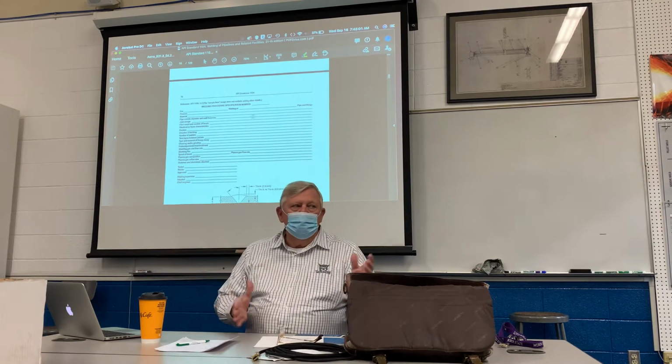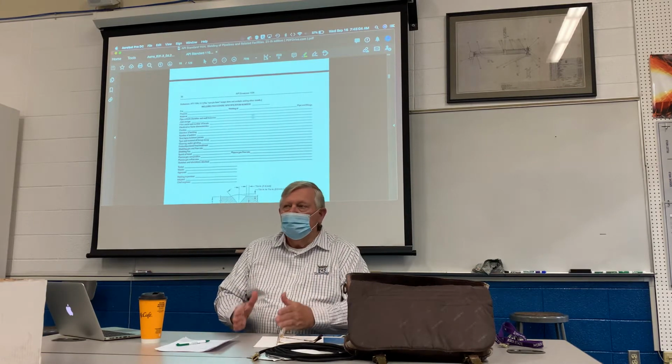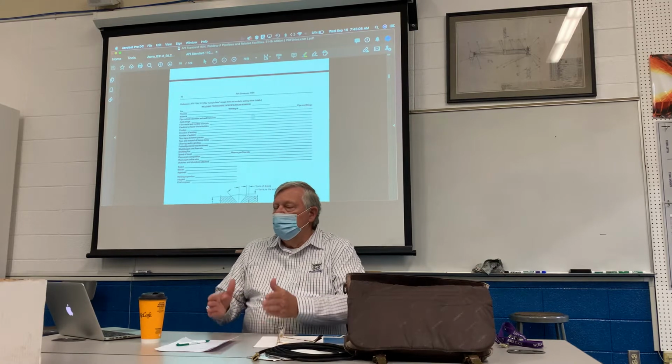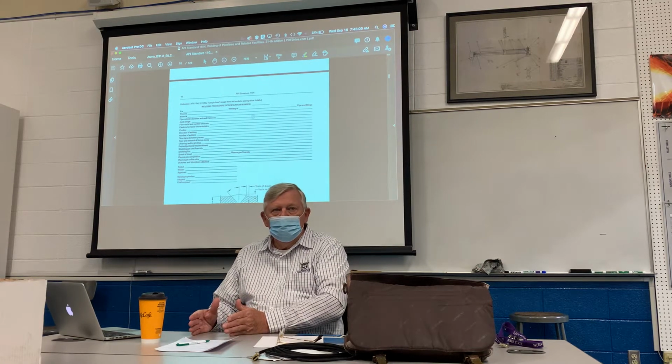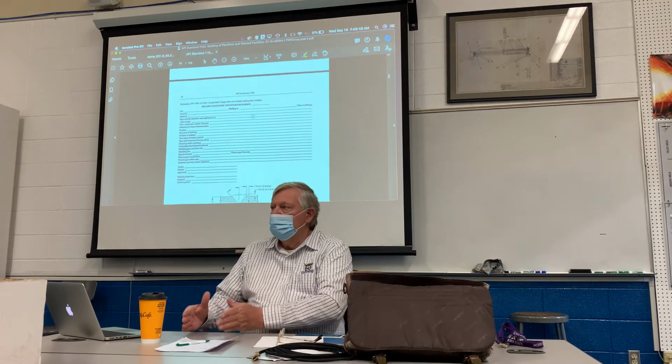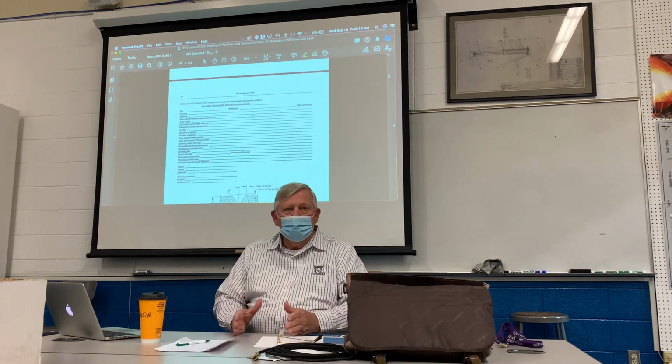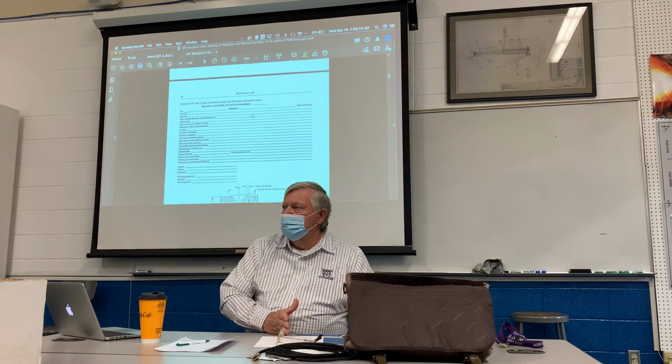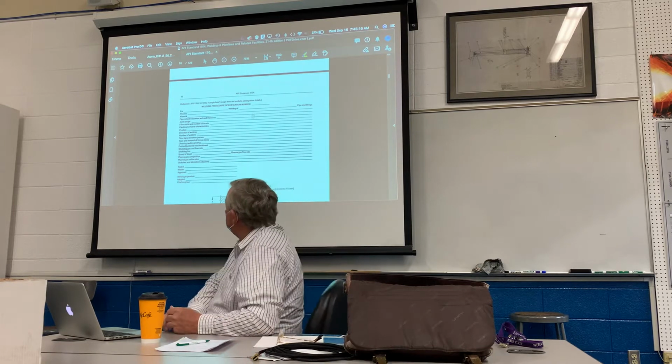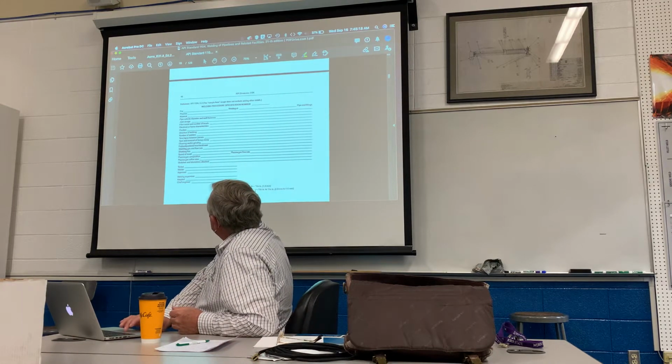So you might want to do something like a 6-inch Schedule 40 X42. So that gives you the pipe size, that gives you the wall thickness, that gives you the grade. So now you've got that information that you can put in for right here. The material is going to be API 5L X42.